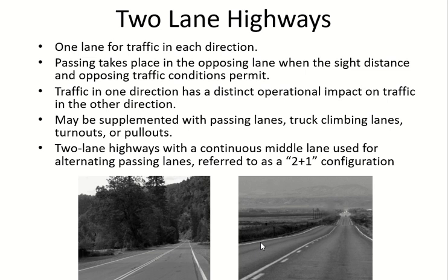So in some cases, you may not have enough sight distance for passing. You have studied sight distance of passing in the highway engineering course. If you don't have the required sight distance, you can make the segment passing constrained. So passing is not allowed in that case. Passing constrained means passing not allowed. Other things you can do is you may have a temporary third lane. So passing will be done from that third lane.